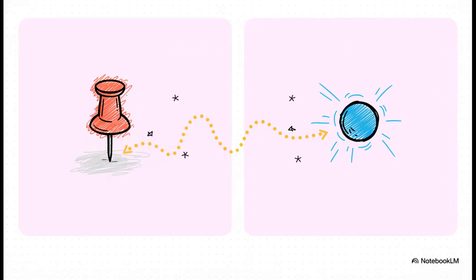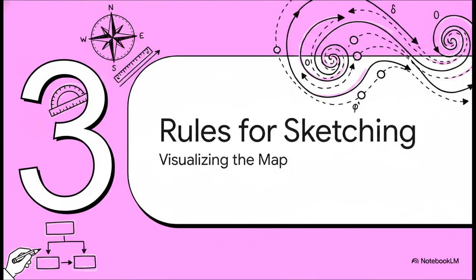Now, the absolute genius of Evans' method is right here. We look at two things. First, open loop poles. These are static, known variables that are super easy to find from our components. Then we have closed loop poles. These are the chaotic, dynamic variables that actually dictate what the system does when it's running. Evans figured out how to use the static, easy-to-find open loop poles to perfectly draw a map of the wild, unpredictable closed-loop behavior. So, how do we draw this map?